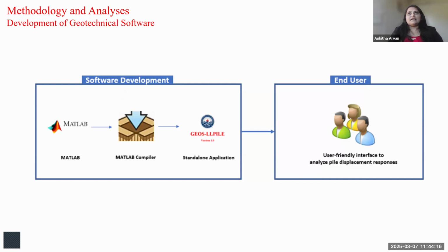So in this case, I saw a niche area where a pile is embedded in multi-layered soil strata, and it is affected by the embedment length into the cap, which affects the fixity. It vastly changes the pile displacement response to the lateral load or the axial load. So the idea was to understand this kind of complexity quite easily.